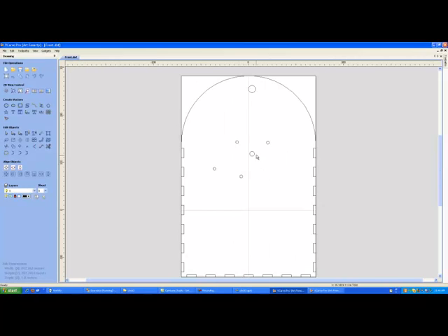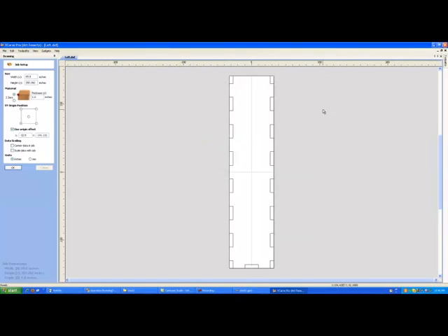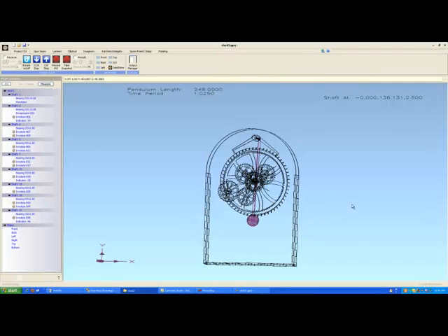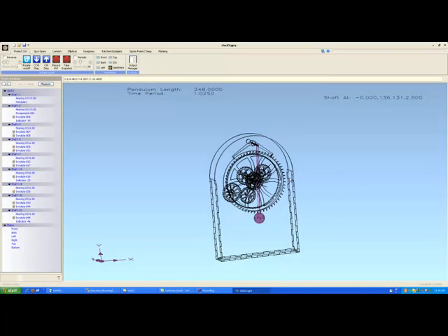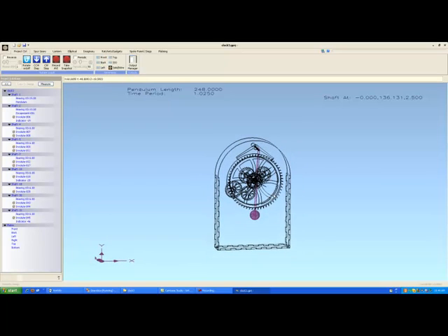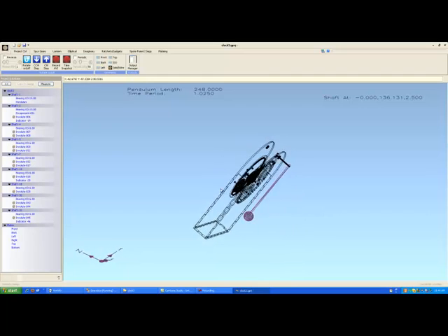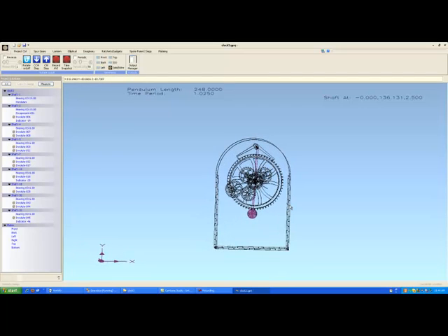All these items will fit together. Your shaft holes will be in the right location, and it's all automatically generated in addition to the compensated output in case you want to compensate for kerf. Of course, if you're cutting these out of wood or metal, you'll have to file or chisel out the corners to make nice square plates for the tabs.